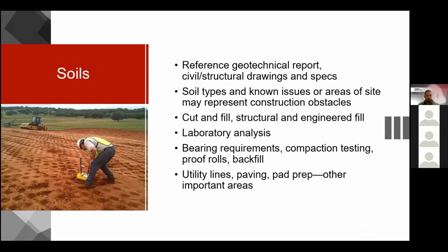Every new build essentially starts with soils. You want to reference geotechnical reports, civil structural drawings, and specs. Review soil types, known issues, or areas of the site that may represent construction obstacles. Are there going to be cuts? Are there going to be fills, structural or engineered fill? Laboratory analysis. We have proctors and soil classifications.